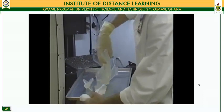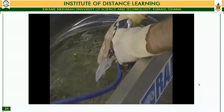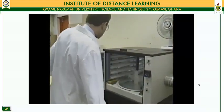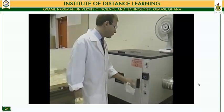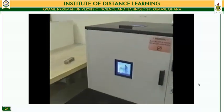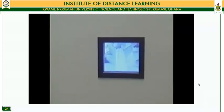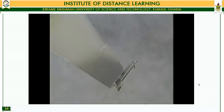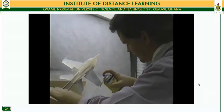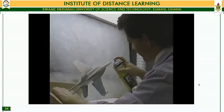So we need to remove it from the platform, rinse it in a solvent to get the uncured liquid off, and then we have to do some post-cure. We have a cover that is about like a tanning booth that puts off ultraviolet light and finishes curing the part. The part is actually deliverable in that state, but occasionally we have people that want to have a finished part where it's painted.